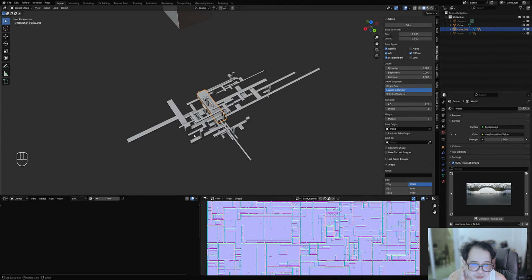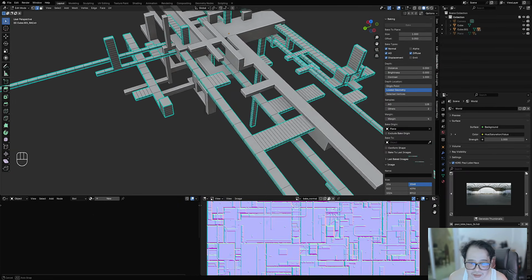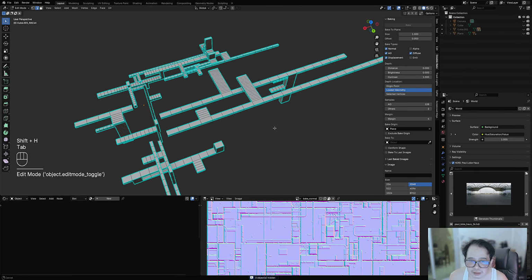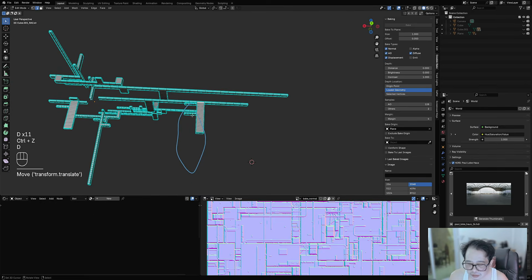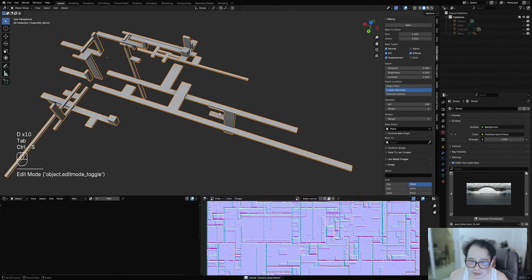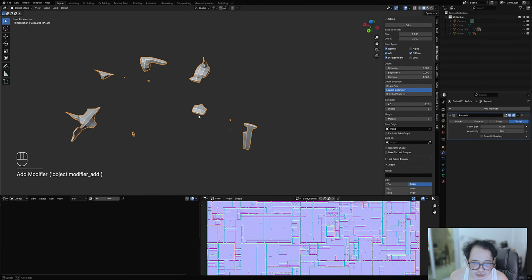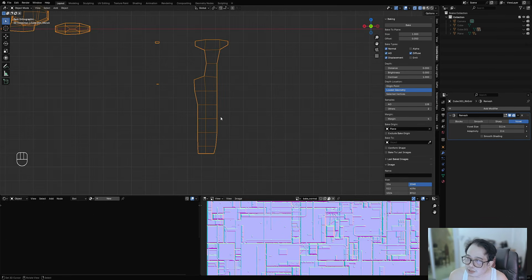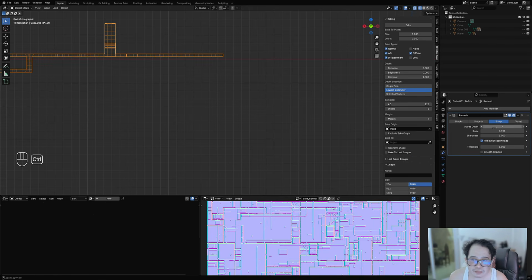Okay. Now I need to actually make sure that these are evenly sized and square, which this is not. So this part here is going to pose a problem. So let's try remeshing to create those evenly sized faces. Generate remesh. Let's go to wireframe to view the resolution. Smooth shading, sharp, and increase the octree depth.